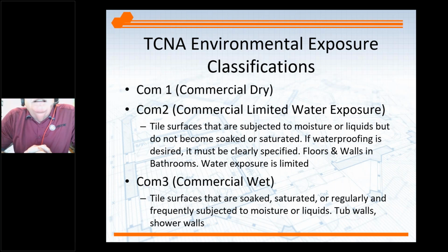Well, the architect at the meeting that we went to thought they had the contractor right here, because he said, look, I put in any wet areas, you should be using waterproof membrane, cement adhesive, cement backer board. He said, bathroom's not a wet area. You didn't tell me they were steam cleaning these. If they did, I would advise you to use those things.